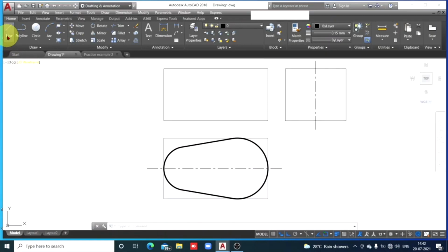Now to establish center, you are going to draw center lines also. So here, check here. When you move cursor to the larger curve, computer is showing us the center for that larger curve. Check. So move cursor to the center. Don't click it right now, because if you click it, a line will start from the center.